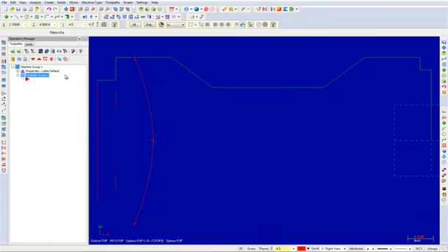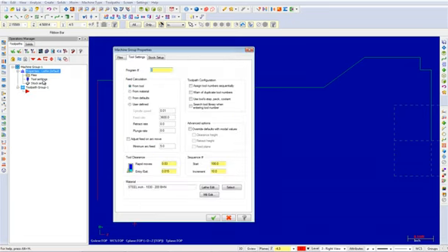Then select the plus next to Properties and pick Tool Settings from that expanded list. Input a program number of 8 and enable the options Assign Tool Number Sequentially and Warn of Duplicate Tool Numbers. You can now select the Stock Setup tab.